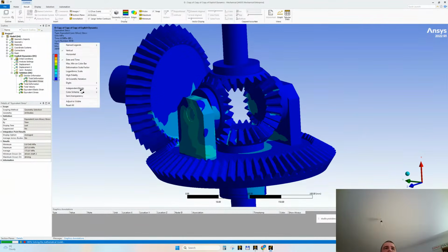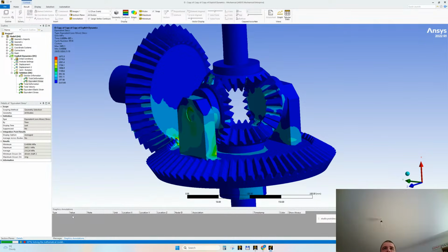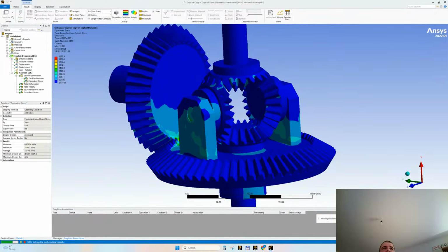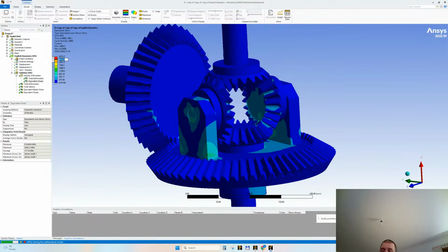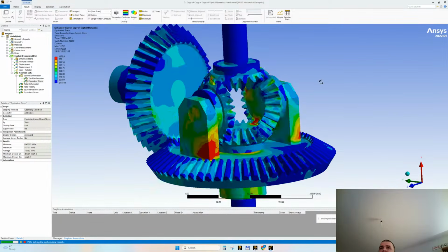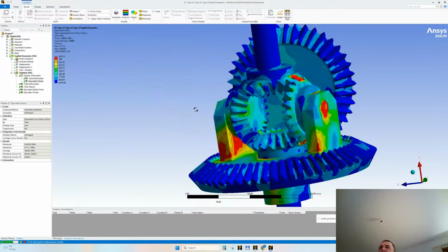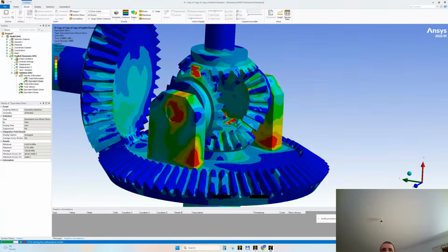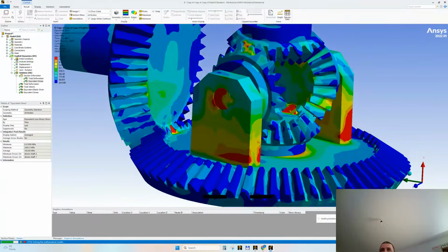We have so high stress because I have used the linear stainless steel. So my advice for you is to use, in explicit dynamics, always use nonlinear materials, yes? Let's make here 500. Let's be a little more generous.